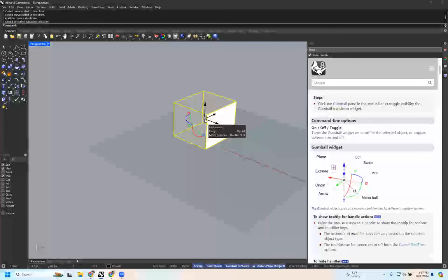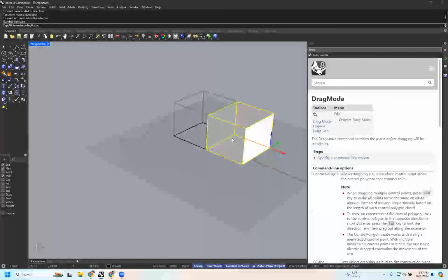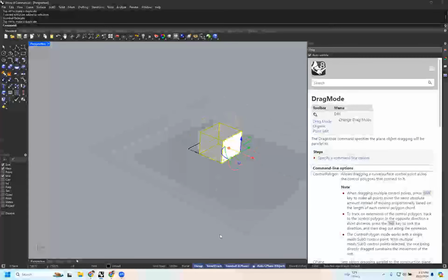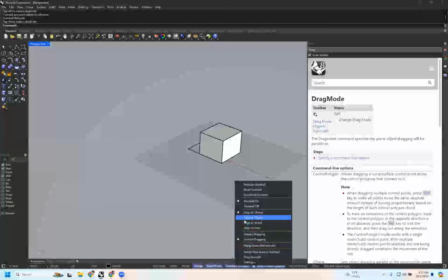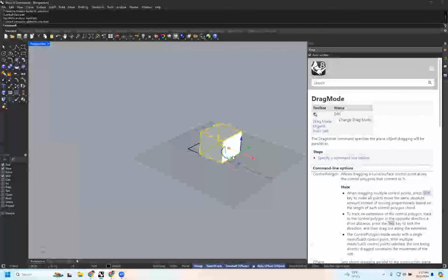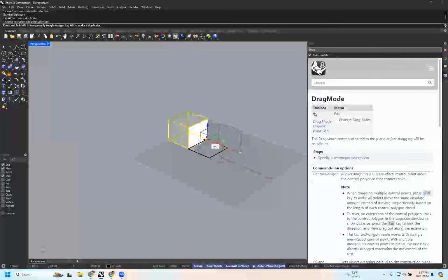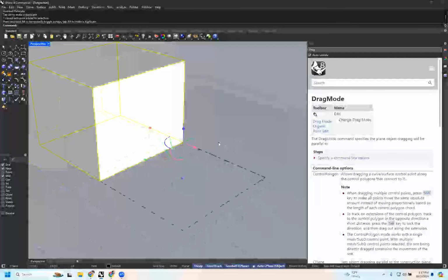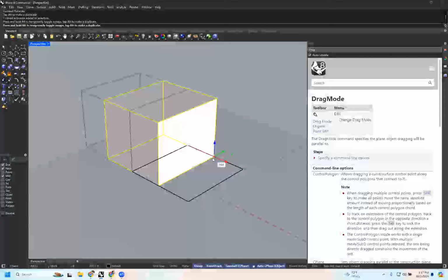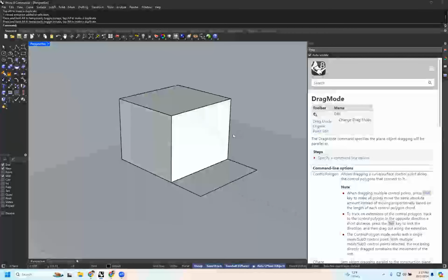So if I wanted to move this over here, I could drag. It also has a feature down here. The gumball can be turned off kind of down here. And if you right click, it has some additional features and settings that you can mess with. Align to object is a really good one, but also snappy dragging. So it'll snap to other objects that are in your scene. So that's usually how people use it, but there's a number of ways.